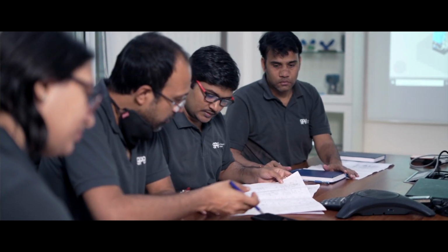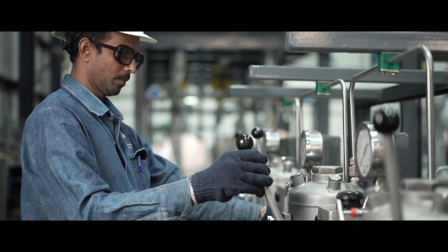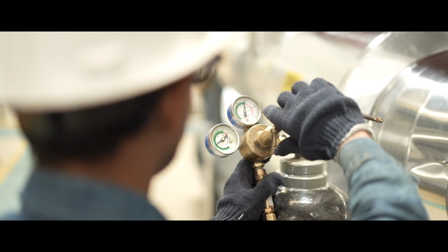Having decades of commissioning experience, we understand setting up a process plant is a complex job involving multiple stakeholders. So we are offering comprehensive factory acceptance test at our facility with the help of third-party independent agencies, with engineering consultants and sometimes our customer. During the FAT, we are doing electrical testing like PLC panel and MCC panel testing, and doing a pneumatic test with nitrogen.